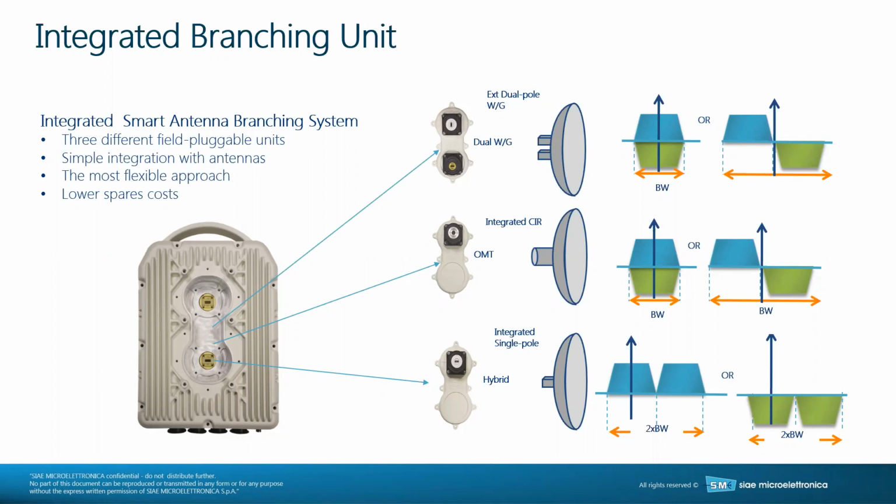So if you've got a legacy network, maybe you've got some older radios, you want to just upgrade the radios and keep the antennas, we can put the ALFOplus2 radio next to the antennas, run a couple of pieces of flex waveguide, and then operate in XPIC mode or operate in adjacent channel, adjacent polarity mode, ACAP mode, maybe channel 1 vertical, channel 1 horizontal, or maybe channel 1 vertical, channel 2 horizontal.